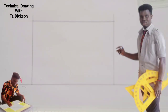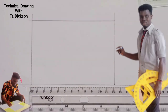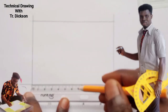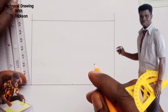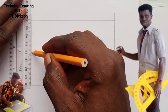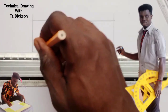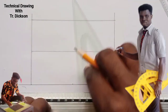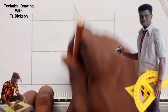Now I am to bisect or divide a rectangle into 2 equal parts on both the major and the minor axis of the ellipse we are intending to draw. Right, so 120 divided by 2 will give us 60, and then we have at this point, and 80 divided by 2 will give us 40. So let's see, we have here 1, 2, 3, and 4. So I fix the point here. Now I work with my T-square and set square. The T-square draws horizontal lines, so I have this drawn already, and the set square alongside with the T-square will give us the vertical line, which makes the major and the minor axis.